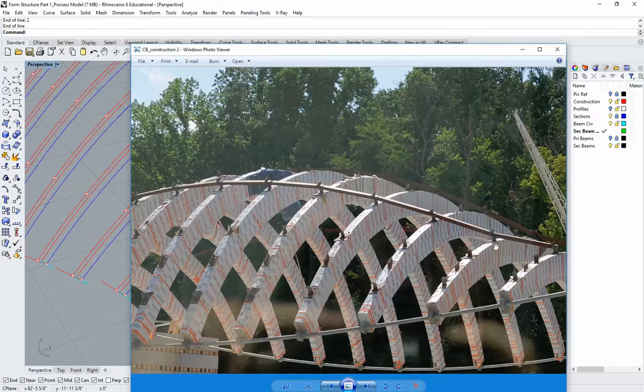I don't know exactly how this is constructed, but I'm assuming that there's a detail in here that allows for a little bit of forgiveness with regard to the form, because here you've got a cable which can easily sweep through this cylindrical connection and be curved. There's no twisting involved here because it's a cylinder. This is a different story. This is a harder thing to build because the angle at which it is offset from this beam is not the same angle that it's offset from that one, and that's going to give it your twist unless you have something in the detail to support that.